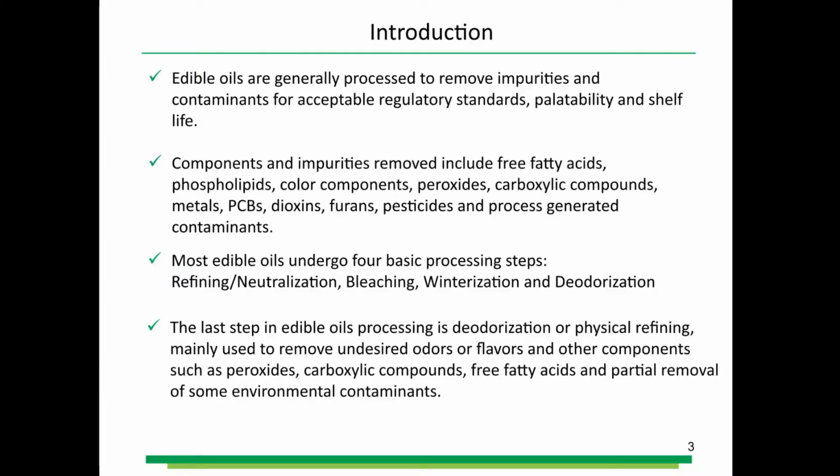Most edible oils undergo 4 basic processing steps: refining or neutralization, bleaching, winterization, and deodorization or physical refining. The last step is usually used to remove odors or flavors, and in the case of physical refining, to remove free fatty acids and other environmental contaminants. And it is in this last step where short path distillation has a great deal of potential.